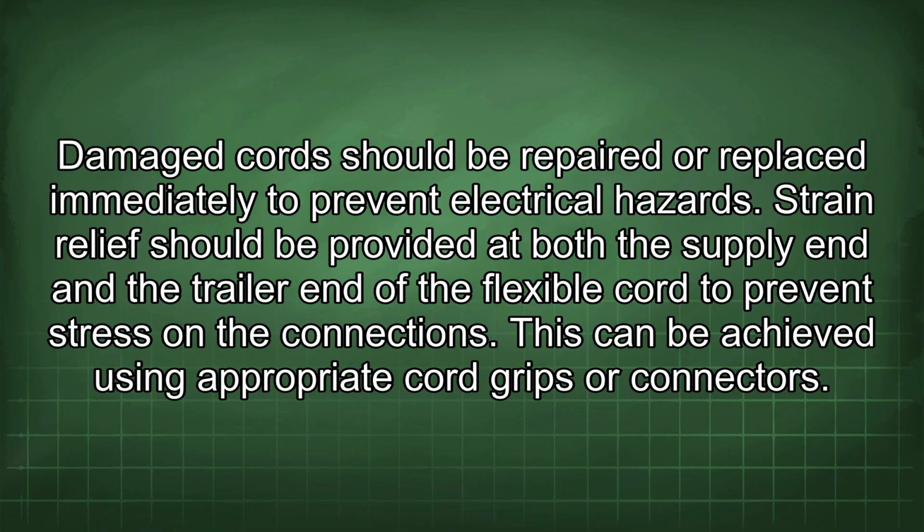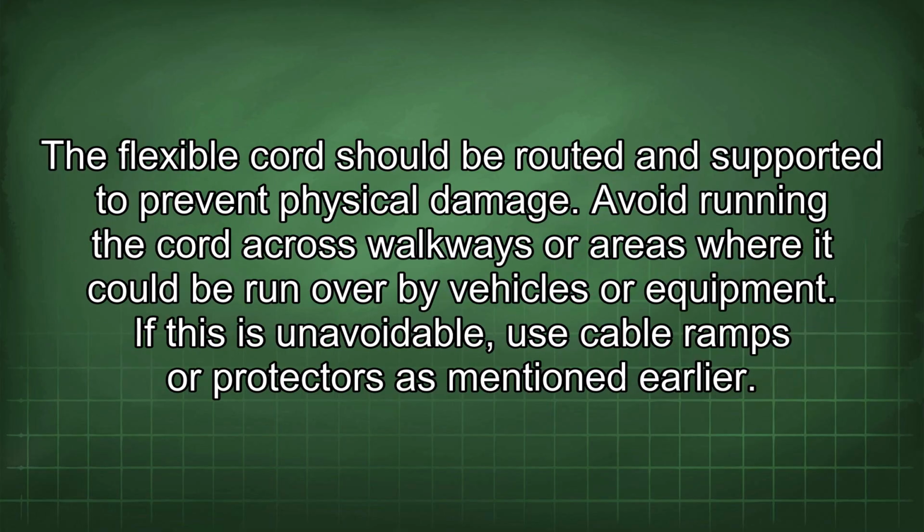Strain relief should be provided at both the supply end and the trailer end of the flexible cord to prevent stress on the connections. This can be achieved using appropriate cord grips or connectors. The flexible cord should be routed and supported to prevent physical damage. Avoid running the cord across walkways or areas where it could be run over by vehicles or equipment. If this is unavoidable, use cable ramps or protectors as mentioned earlier.